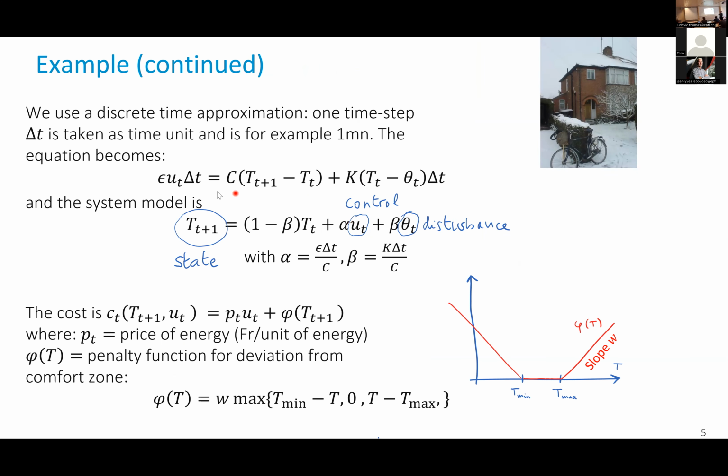Well, we discretize this model, which the physicists give us in continuous time. We make a second approximation by making it discrete time. At the time scale that we're speaking of, the temperature of a house, it's very easy to discretize, right? We're not modeling the temperature inside a living cell, for example, where there can be large gradients at a microscopic scale. Here we are at a macroscopic scale in terms of temperature, so temperature doesn't change significantly within seconds or even minutes. So the discretization is very accurate.